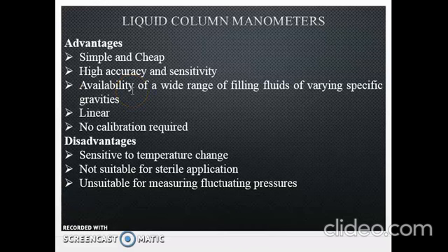If we consider the advantages of liquid column manometers, they are simple and cheap. High accuracy and sensitivity can be obtained if the manometric fluid is chosen properly. A wide range of filling fluids of varying specific gravity is available. The response of the liquid column manometer is linear, and the most important advantage is that no frequent calibration is required for liquid column manometers.